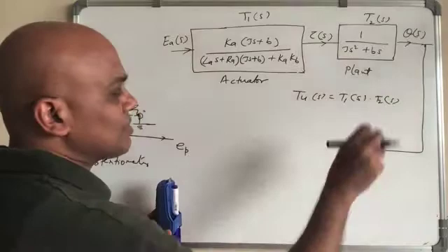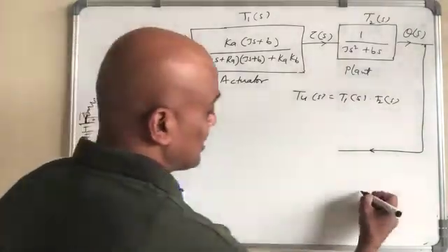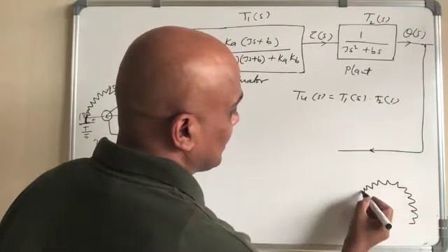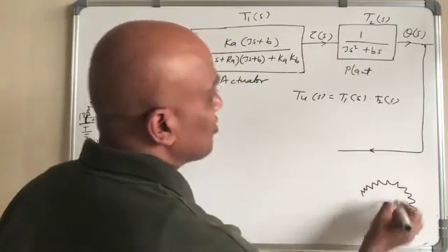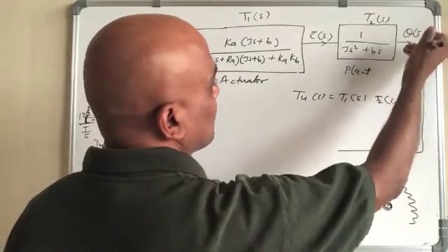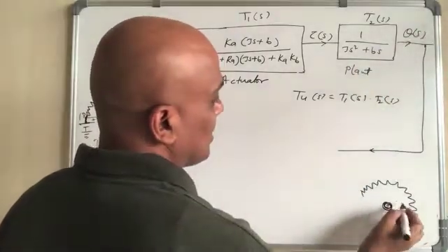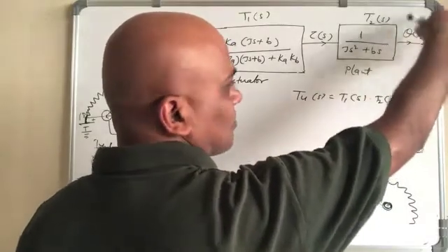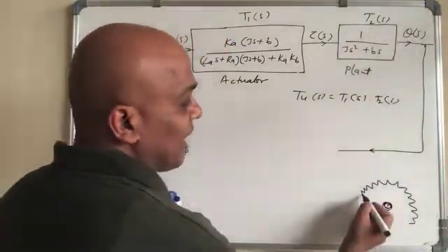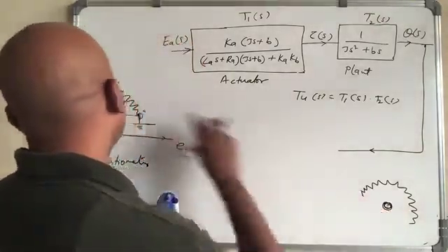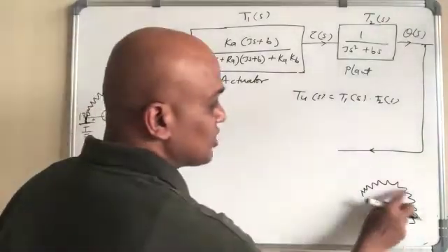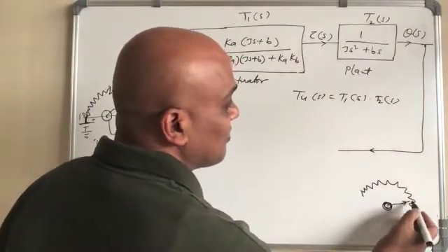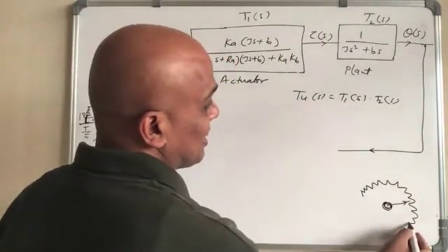The sensor could be in terms of a potentiometer there also. Since you have a motor here, the shaft here, and the load there, the flywheel, on the flywheel itself there may be a potentiometer, and from there you can find out what the angle is.